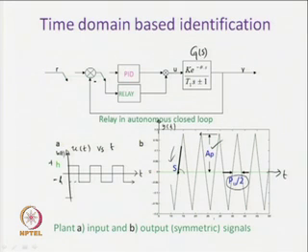So, immediately after the zero crossing, we shall measure the slope of the sustained oscillatory output of the relay control system. The relay induces this type of typical signal, and we shall make 3 measurements, namely S, the slope of the output signal at the zero crossing, Ap, the peak amplitude of the output signal, and the half period of the output signal given by Pu by 2.